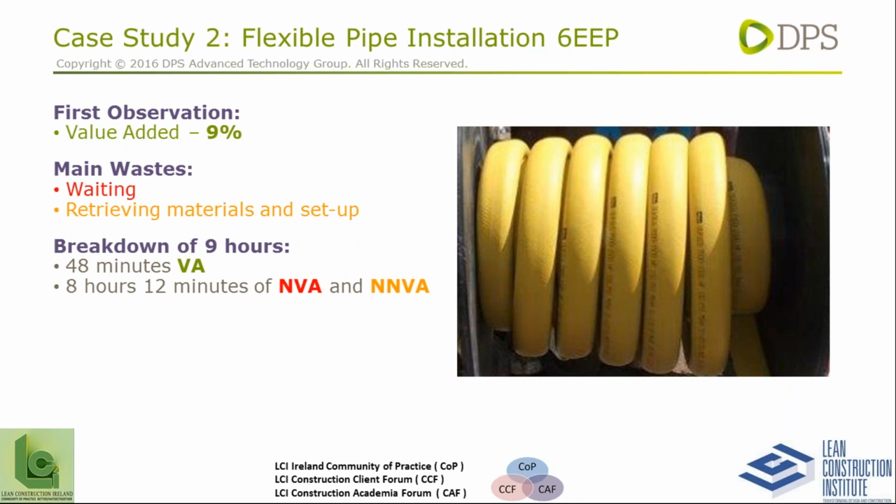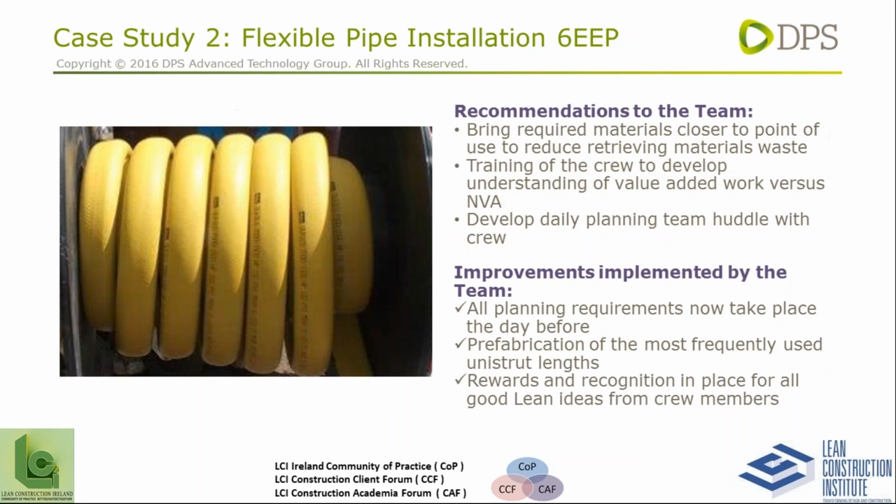So let's look at a breakdown of the 9 hours. 48 minutes were value added, 8 hours 12 minutes were non-value added and necessary non-value added, so that's the waste, the opportunity. The recommendations that we give to the team: bring the required materials closer to the point of use to reduce retrieving material waste. Training of the crew to develop understanding of value-added work versus non-value-added work.